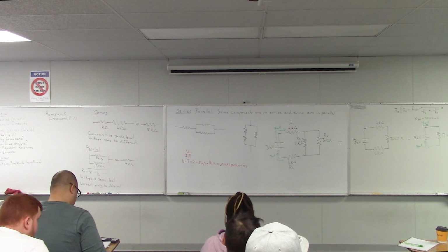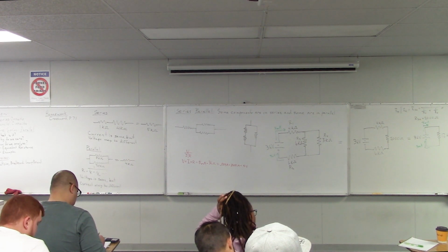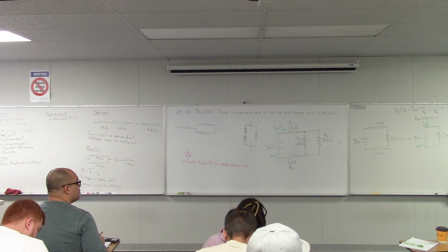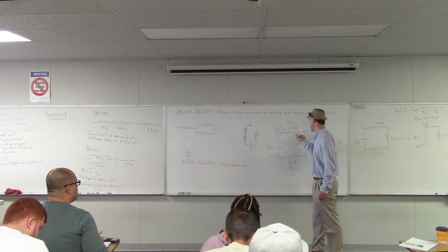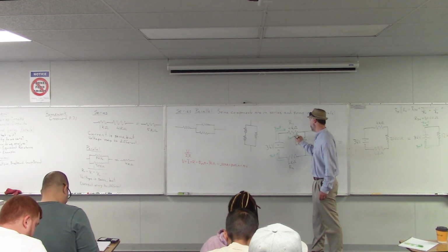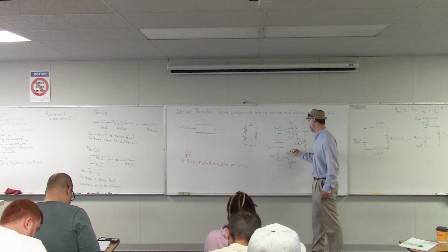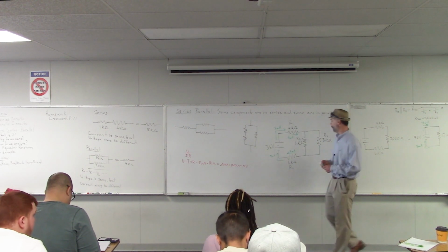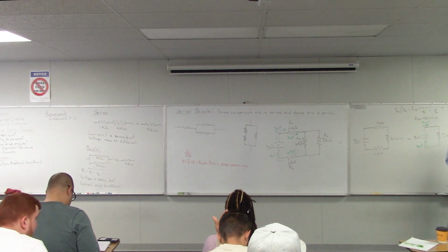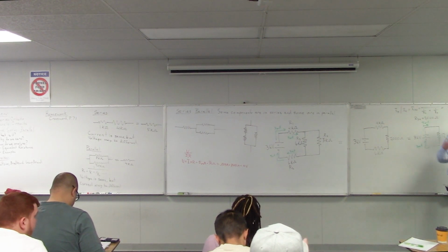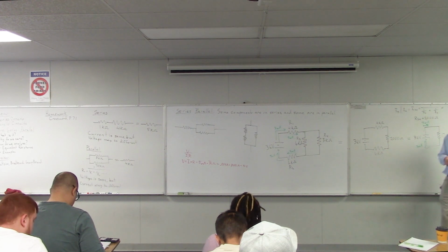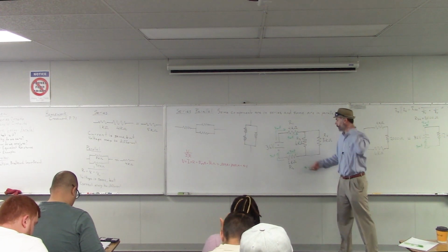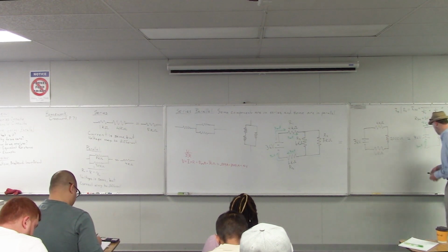Yeah? Okay. All right, so we got the 3 milliamps for both of those, so we can draw those in. So we have 3 milliamps there, and 3 milliamps flowing down there. So what could we work on next? Yeah. We could either do resistor 1 or resistor 2, since we know that we can find their voltage, because we know the current and resistance. Exactly. So we can use Ohm's law with R1 or R2. So let's just start with R1, since that's on top.